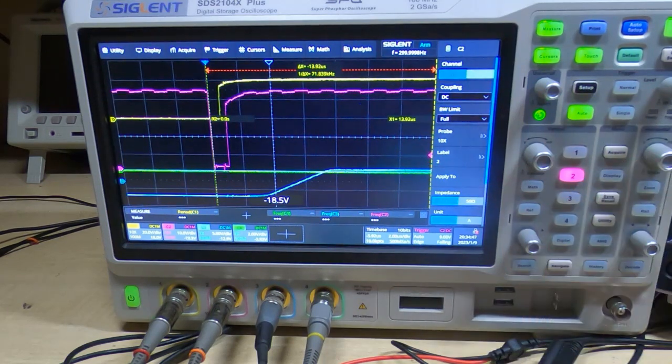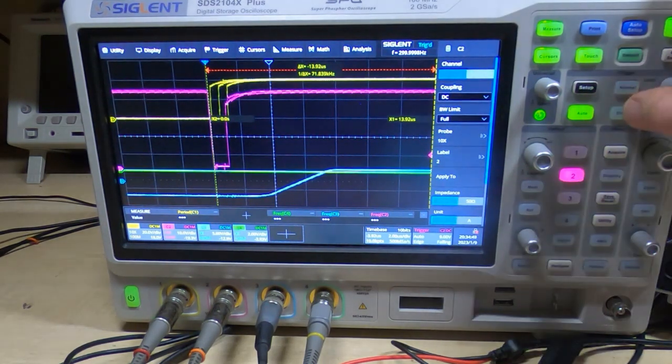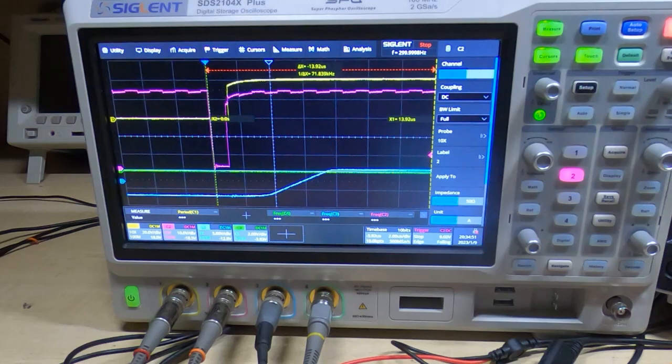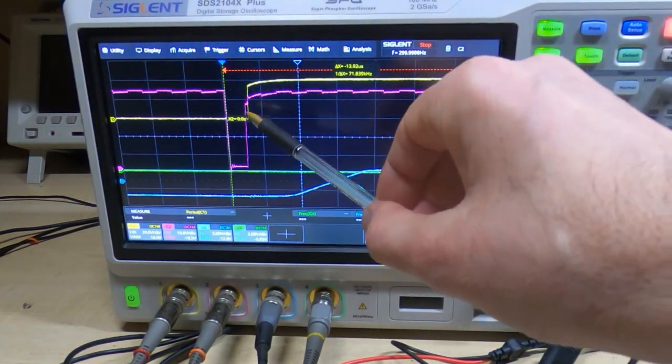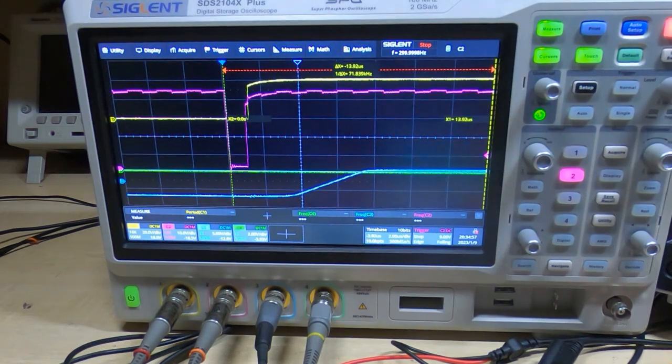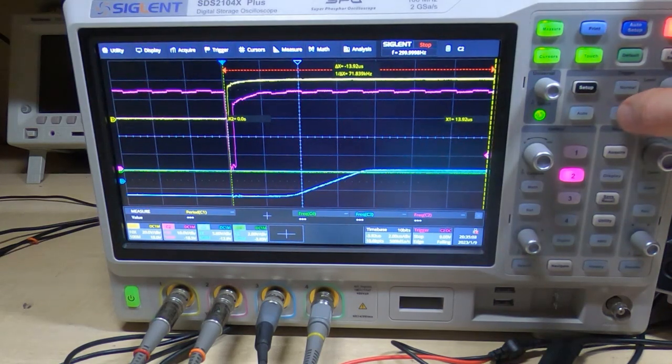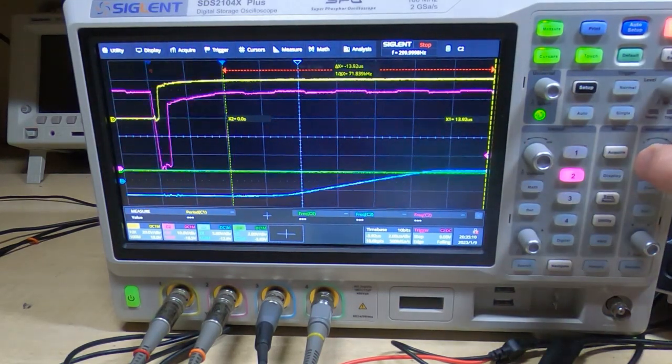So notice that if I do single captures, this particular clock edge, the yellow edge, is outside of the start pulse, and if we go even shorter on the start pulse, so I'll go down to about 300 nanoseconds, which is about what we'd get from the Z80, do another single capture, we'll zoom in a bit further.